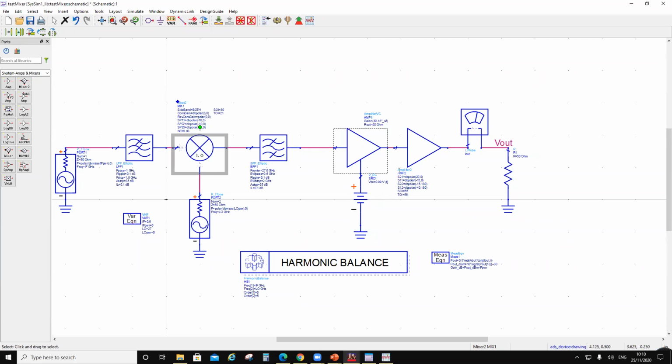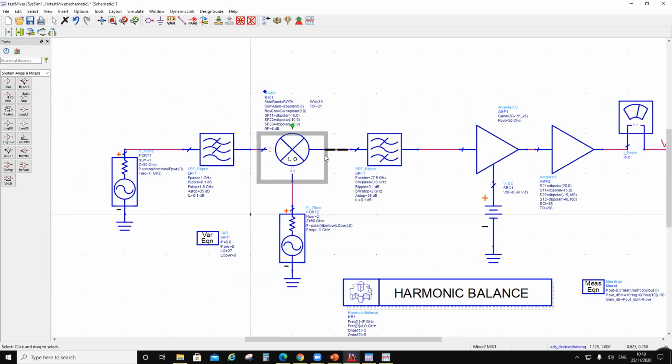Now the question is, that is welcome, but if they come back in a distorted phase, that's not welcome. Then people start doing harmonic suppression on this. They will put attenuator pads here, they'll put attenuators. That's a band-aid solution. That's because you didn't design it properly. A mixer in a chain should not need attenuation pads.